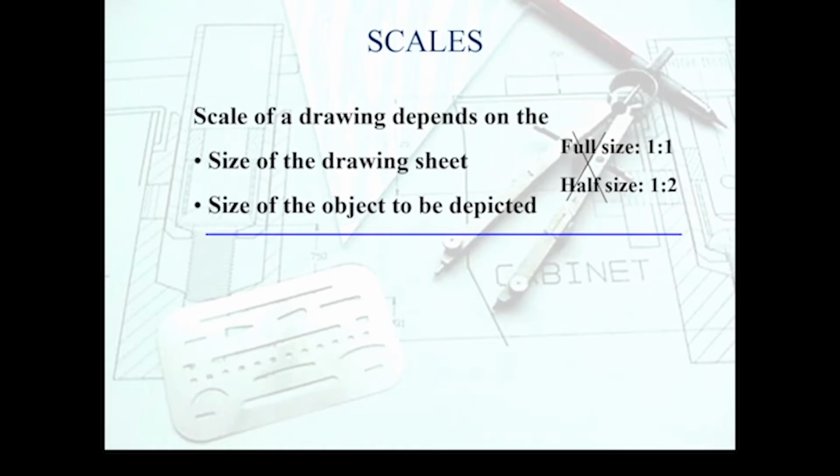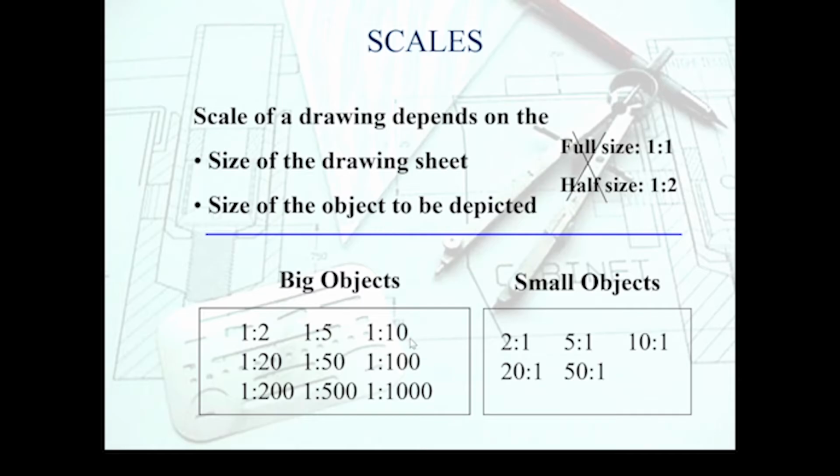A word or two about scales. Obviously we need to include that for very clear reasons in terms of trying to fit large objects on a small bit of paper. And you use a scale like this, which is 1:2, probably half scale. Having said that, we tend to avoid non-technical terms like full scale and half scale. It's very casual language. However, you technically are meant to be calling this 1:1 scale or 1:2 scale. Okay, but we all know what half scale means, what full scale means.